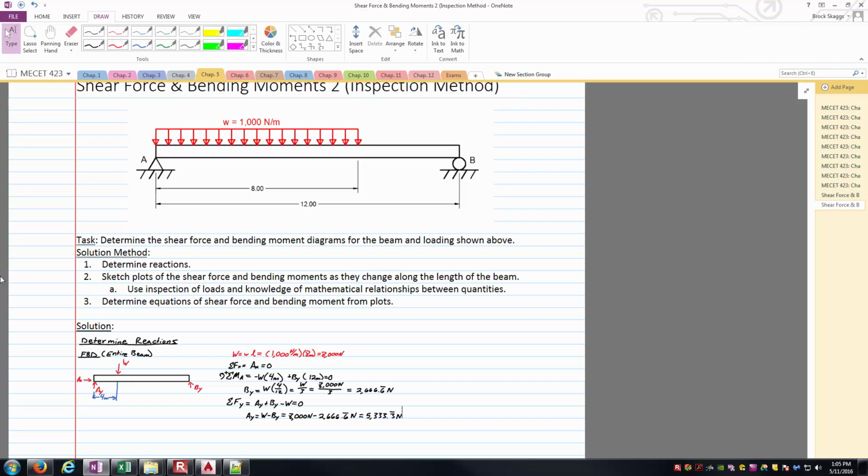That's why I've got A sub x and A sub y there on the bottom left of my beam. And on the far right-hand side, I've got the roller that's rolling on a horizontal surface. Here we know that the reaction force is going to be perpendicular to the surface the roller is sitting on, so that's going to be strictly an upward reaction, B sub y. And then for the distributed load, that is a distributed load in and of itself. But you might notice I've moved it from a distributed load to a concentrated force here, and that's okay.